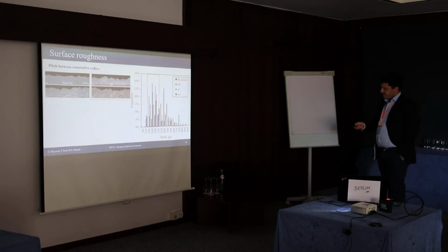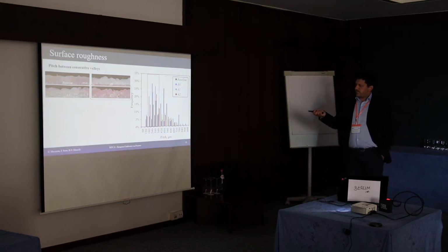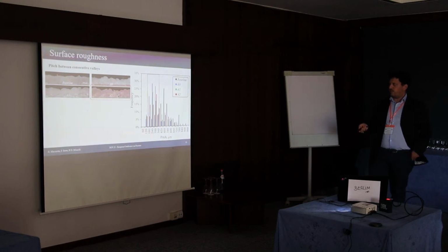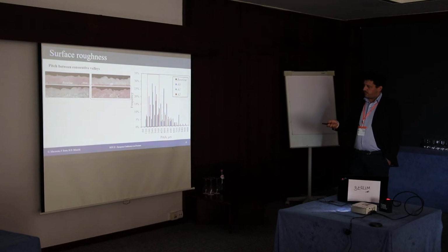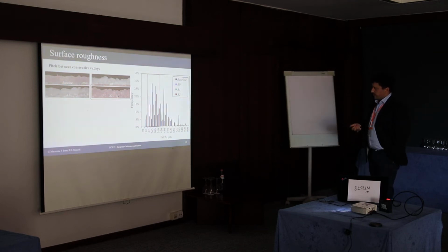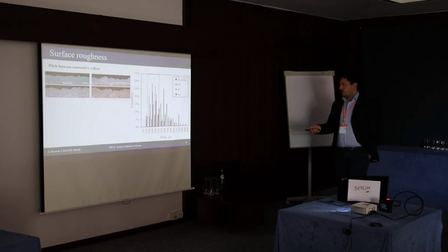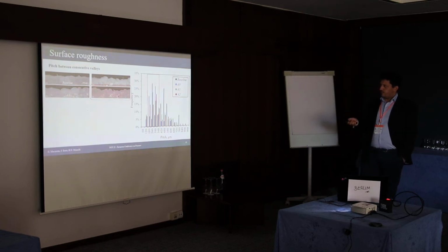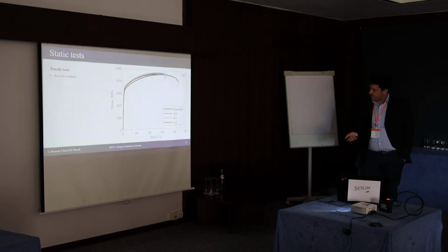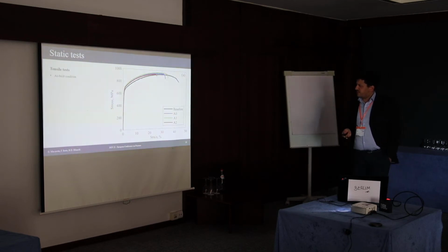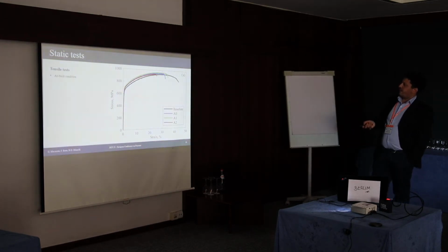the layer thickness. So the difference is that when you move from baseline to ATU process parameters, you have an addition of a short pitch and a long pitch, and the long pitch is between the steeper valleys. You can see here you have these 2 steeper valleys, but you have also this valley in the middle. When we investigate the effect on the stress distribution, we can see also effects of stress shadowing because of this pitch distribution. Okay, I'll show you better after in the finite element simulation.